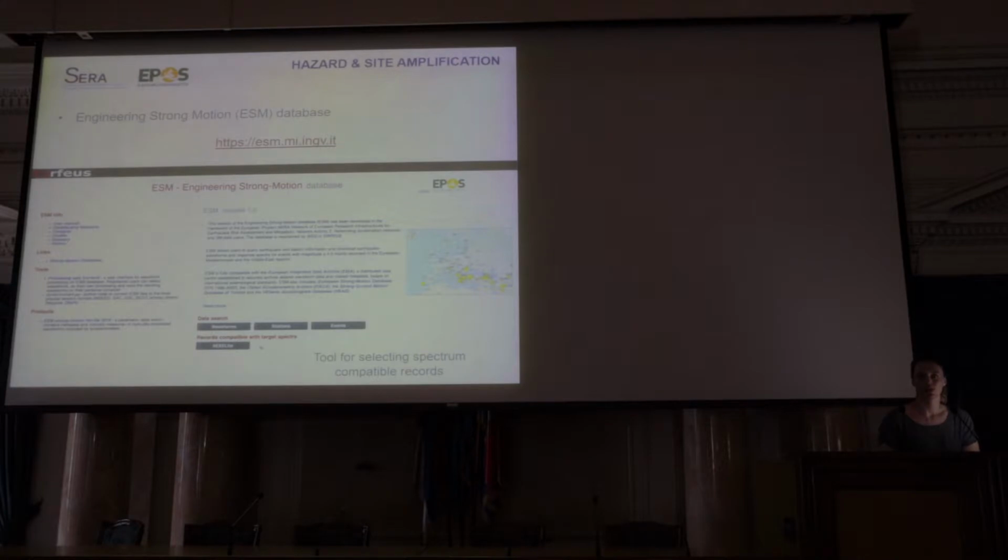I just wanted to spend a few words on the Engineering Strong Motion database. You may not be familiar with this. This is a quite recent database that's been released. This is the link to the website. It includes strong ground motion recordings from European, Mediterranean, but also Middle Eastern earthquakes, and you can download those recordings from the website. It has a feature called Repsol Lite, which is a tool for selecting records to be compatible with a given response spectrum as well. This is quite useful for structural engineers that need ground motion recordings for nonlinear dynamic analysis of structures. They can come to this website and obtain the ground motion recordings.